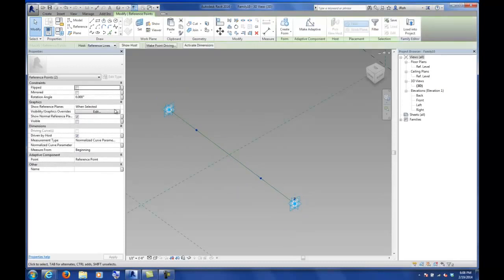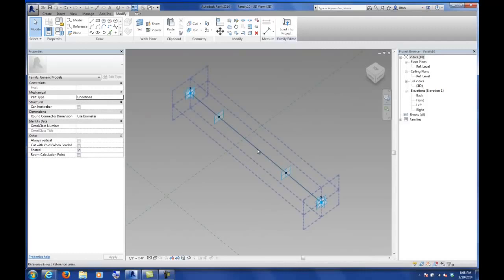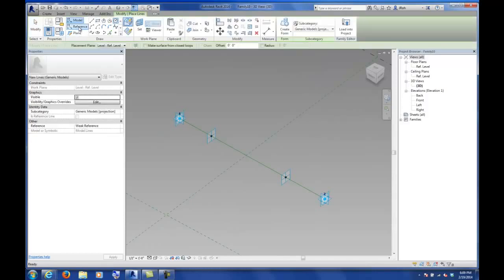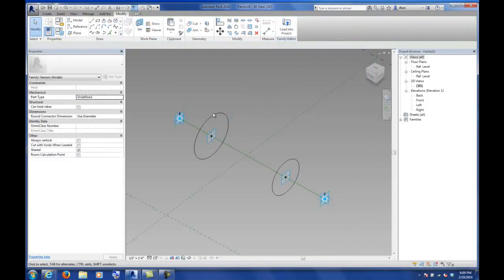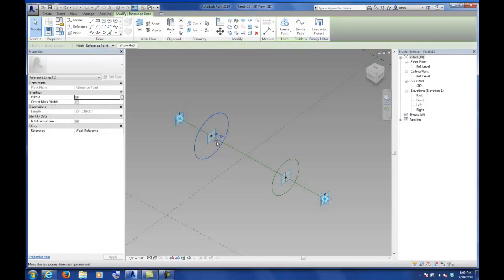But basically what I'm doing is I'm making this pipe that I can actually draw anywhere. So instead of drawing a line, I'm actually drawing with pipes. So you could actually make your own kit of parts that you could eventually snap to things, which comes in handy for structural components and so on. So I'm going to go to Create, Circle, Pick. That one. I'll do another pick. I'm turning both of those into reference circles. And I also want the dimensions, just so we can size them later.